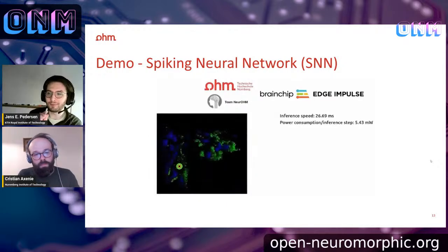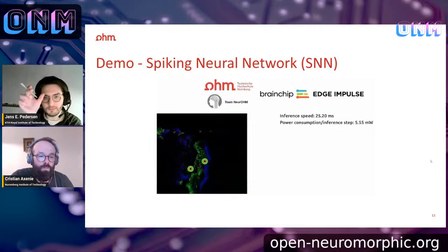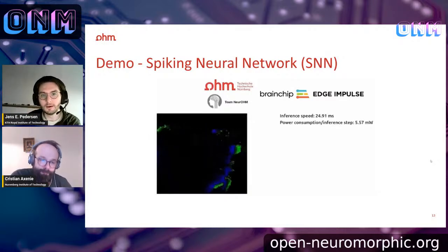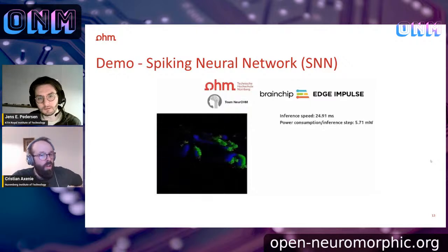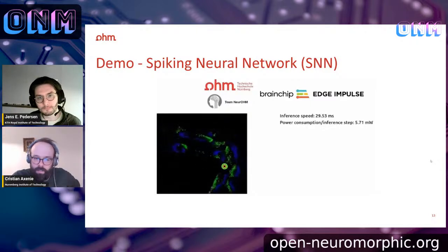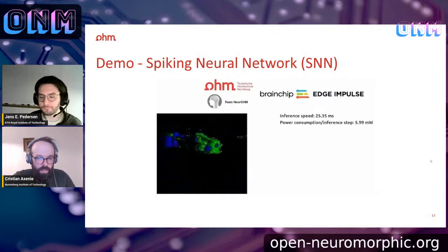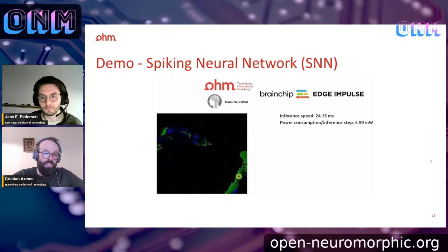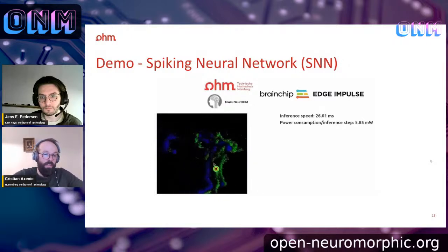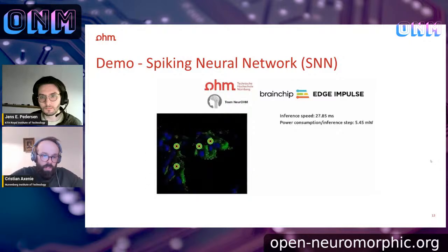That speaks to another question from Gregor. Thanks for all the questions, Gregor. Do you send in frames one by one? So is that a dense representation, or do you have a sparse coordinate representation? It's just dense, like a matrix. A dense matrix representation of events, but aggregated as mentioned. We couldn't figure out how to ingest raw events in Edge Impulse. One can do it, but it needs additional effort, and we didn't want to put it inside.